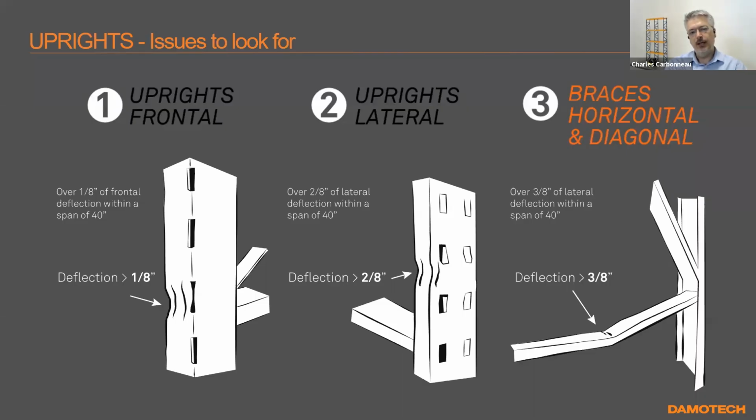And so we come up with this guide, based on a proportion of deformation. We're saying use this 1, 2, 3 rule. 1 meaning 1/8 of an inch of tolerance on a frontal impact. If you're below that value, don't worry, it's a scratch, it's a dent.